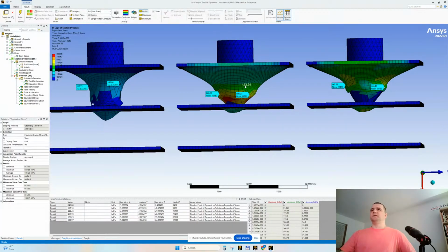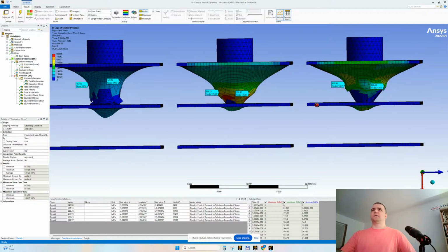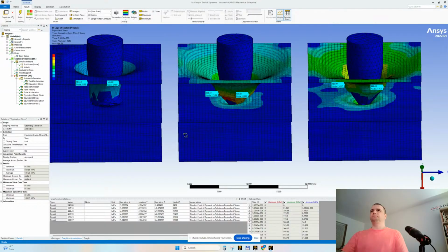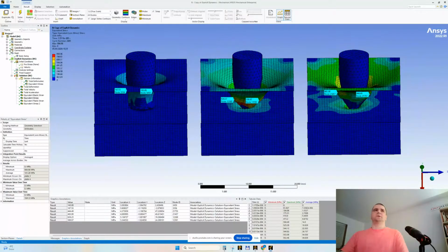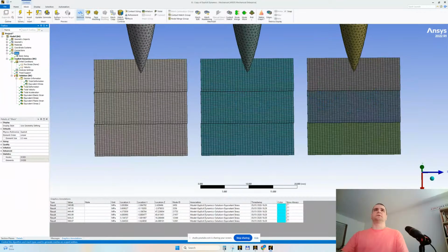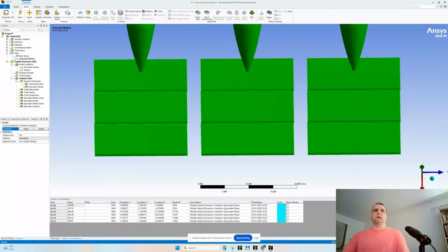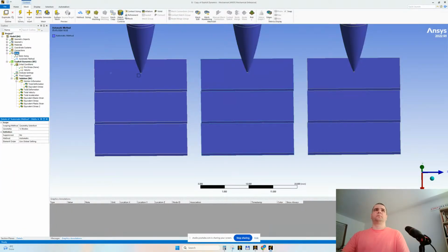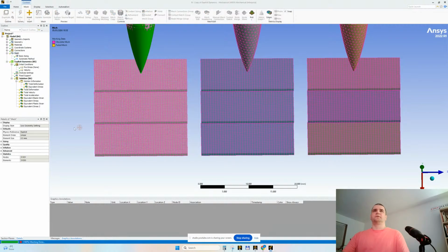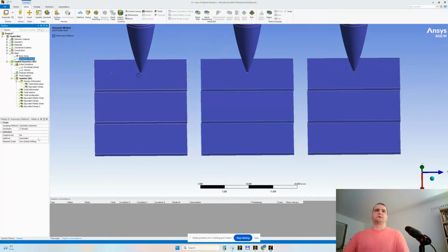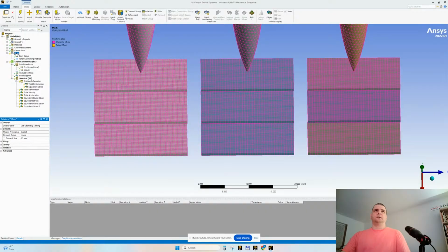So 150, 600, 450, all right. And let's change now the meshing to be tetrahedron overall. The easiest way is click one body, Control A to select all, apply, and it will be everything tetrahedron now. Of course, if we assign a tetrahedron, generate.